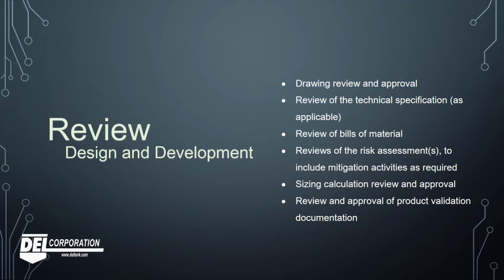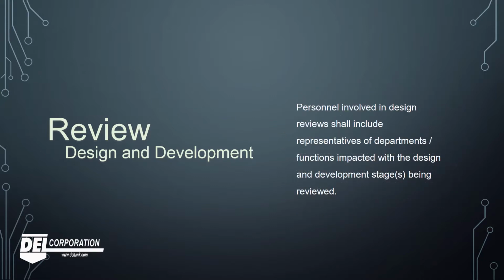Drawing review and approval, review of the technical specification, review of bills of material, reviews of the risk assessments to include mitigation activities as required, sizing calculation review and approval, review and approval of product validation documentation. Personnel involved in design reviews shall include representatives of departments or functions impacted with the design and development stages being reviewed.